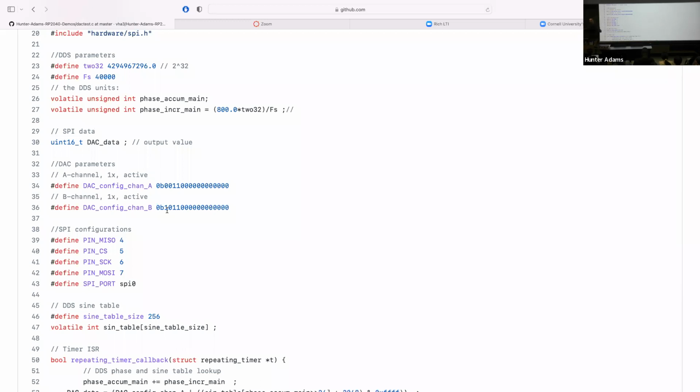So for example, variables that are updated in interrupt service routines, right? Perhaps your code in main is using this variable to do something. The interrupt service routine interrupts and modifies the value of that variable. When you come back to main, you want to make sure that you retrieve the most updated value of that variable from memory as opposed to using some sort of locally cached value. So you'll see volatile wherever you're updating things in interrupt service routines. And we'll see some other keywords, but I'll talk to them as we encounter them in later examples.